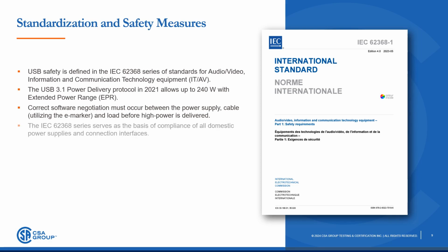The IEC 62368 series of end product safety standards not only serves as the foundation of power supply compliance, but also covers the connection of all interfaces used in information technology equipment, including USB, RJ45, RJ11, and similar. Aside from the IEC 60335 series of standards for the safety of appliances, other comparable end product standards determine compliance based on the design and construction principles of IEC 62368-1 compliant power supplies, with only minor modifications, such as specific markings to indicate the intended application.